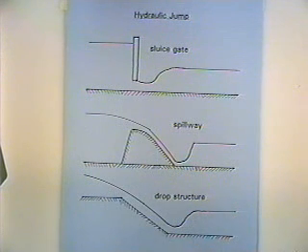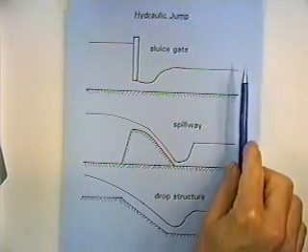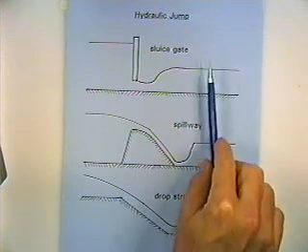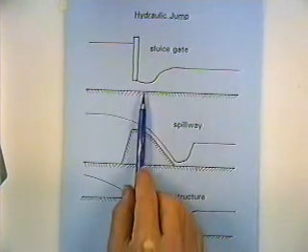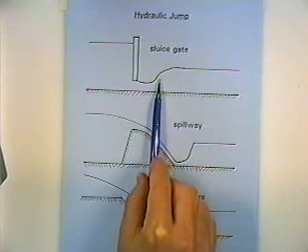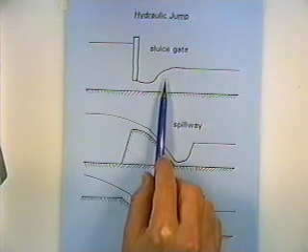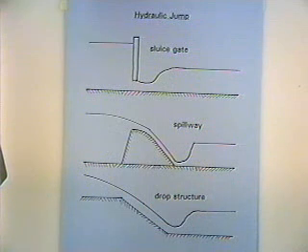The water is really barreling out of that culvert, or out of that conduit, or whatever the gate might be. And then downstream we have tranquil flow, relatively flat slope, subcritical flow, and to get from the supercritical to the subcritical, it's going to do it quite abruptly in a hydraulic jump. Another situation with spillways.